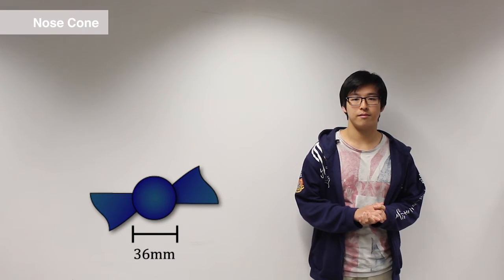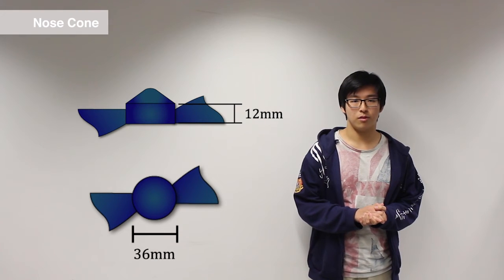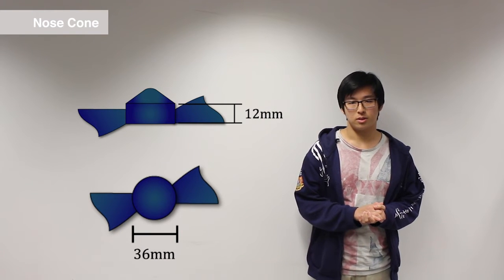The cone was designed with the smallest possible diameter of 36mm in order to maximize the length of the blades. The small hop and the minimized length of 12mm reduced the overall weight of the turbine, while still guaranteeing the structural integrity during the test.